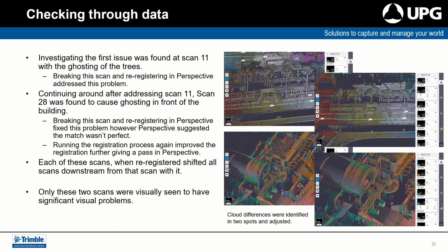Now, to fix this problem, the scans were broken in Perspective and re-registered using the 2-point registration and the manual registration type, and this allowed the scans to match up correctly, and it helped to remove a significant part of the error.